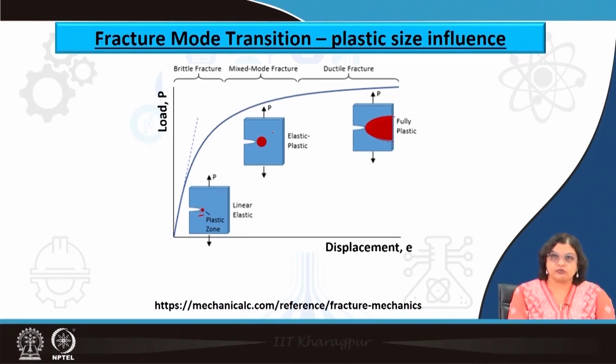In reality, in most cases the failure occurs in mixed mode conditions, and we often need to use such relations, but for lab scale testing or for the very basic concepts about fracture toughness, we still prefer to use the linear elastic fracture toughness. Now, when would this linear elastic fracture toughness be valid and when is it not?